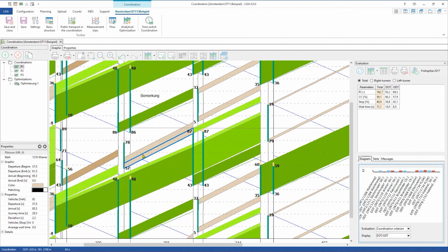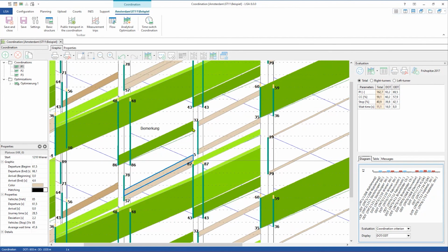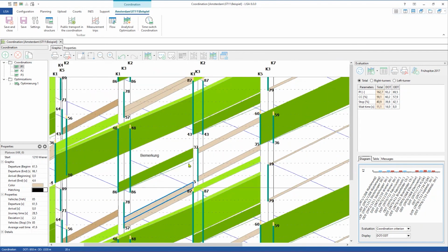And you see this platoon. These cars are separated into two platoons here at the next intersection. So the first platoon can drive through green and yellow, and the next platoon will wait on red. Also this platoon here is grouped with this platoon, and these two platoons start at green beginning right before the green wave, or the platoon of the major green wave, arrives. So we have enough time that we have no queue back.